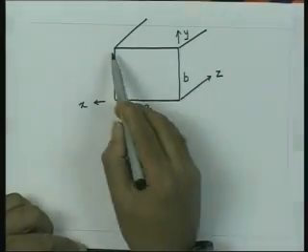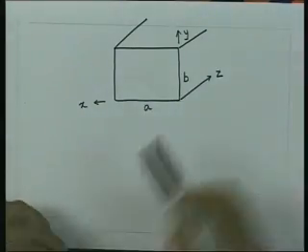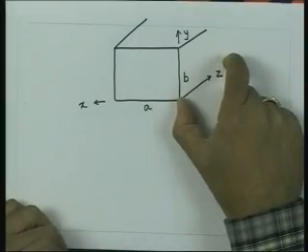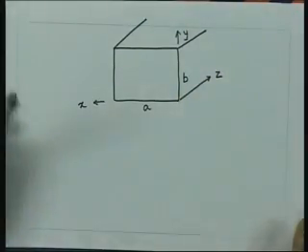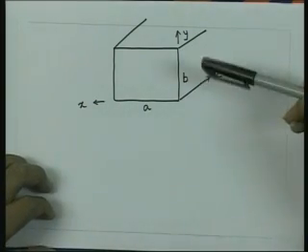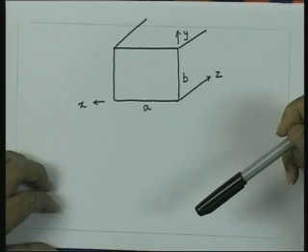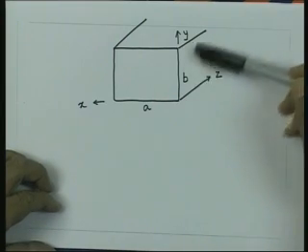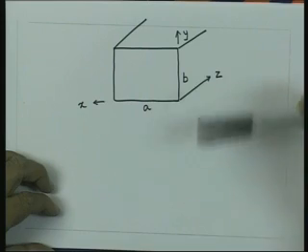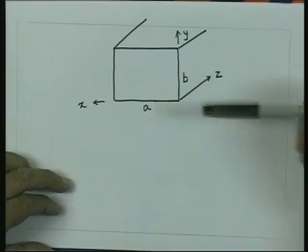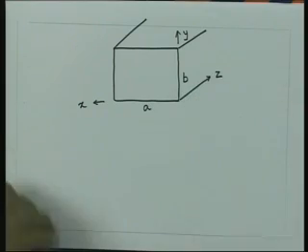So what we do first, we calculate total power, because I know now the cross section. I take per unit length of this waveguide and calculate the loss per unit length. Again we use the same argument, since at every location the field is going to vary as a function of time sinusoidally. We take the peak value of the magnetic field and just take the RMS value from there, and then you calculate what is the power loss by integrating over the length of the waveguide.